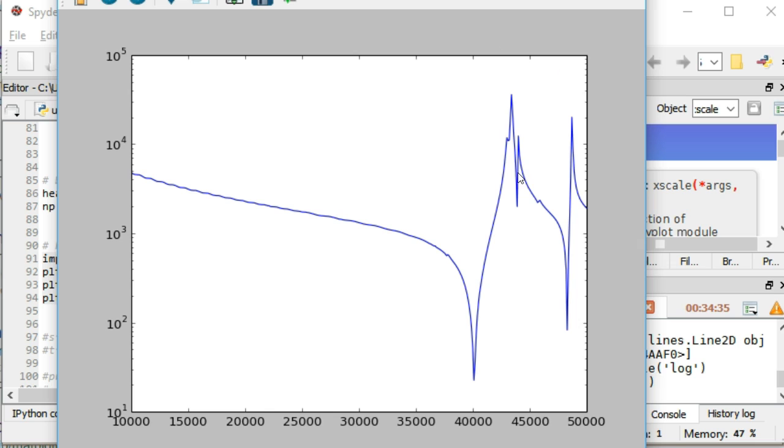What's going on here is probably other resonances occurring, minor resonances. Right now the transducer is sitting by itself, but its behavior significantly changes when you adhere it to your structure, which will be holding some type of solution and whatever you're going to clean inside of that solution. So when you attach it, it changes the boundary conditions and changes the resonance frequencies, all of them differently, including these parasitic, non-ideal modes, which are a byproduct of its having many resonance frequencies, and the main resonance, which is an extensional mode.